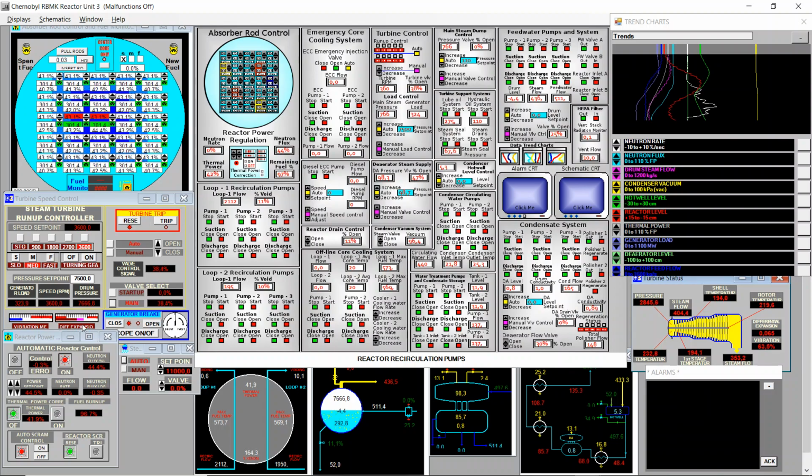And we see this here graphically. We have these 2 red lines to the left and to the right. To the right will be when the rotor is more hot than the shell, to the left the contrary. So when we reach this red line, we will be in trouble. We'll create a lot of vibration. For the moment it's still fine, so we can keep increasing power set point.